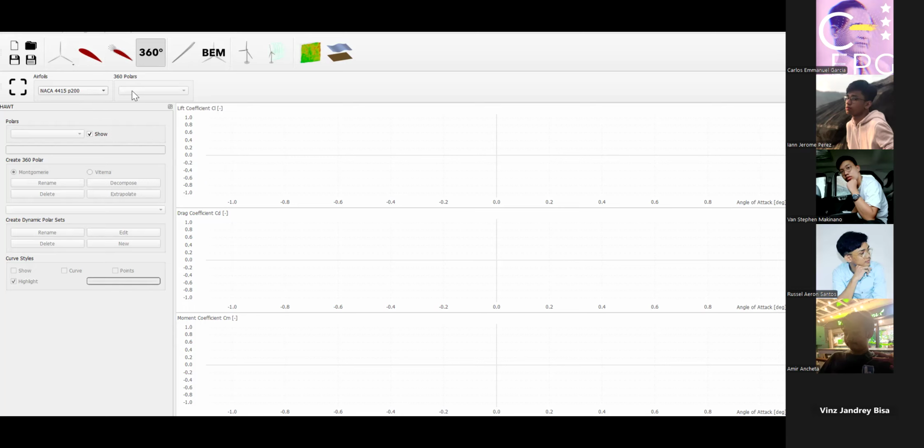Compare them. Now again, this 360 module is not part of the graded activity, but this is important for examination of the turbine. Because this 360 degrees extrapolation is what you will layer together as you reassemble the blades. If you recall, QBlade's method is to chop the blades into 2D segments, then reassemble the blade along with the 2D data. So this extrapolation is part of that. This is what you actually reassemble when you're assembling the blade.